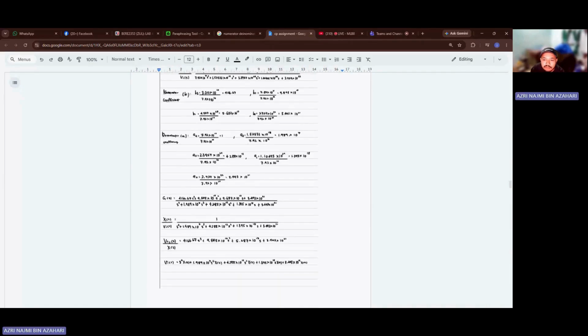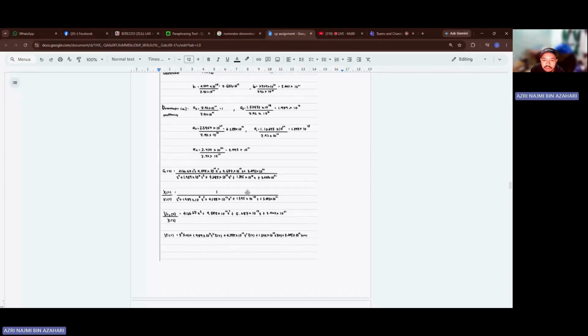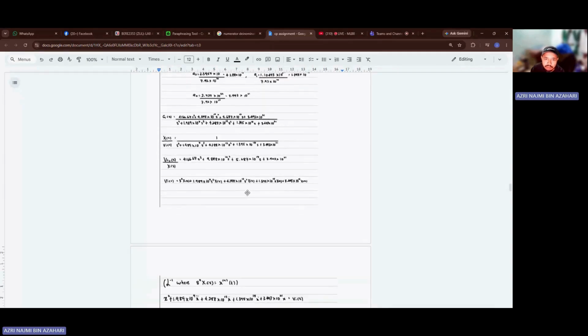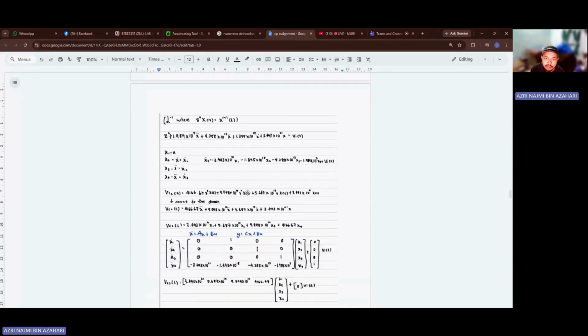By applying the inverse Laplace transform, the denominator polynomial is converted into a fourth-order differential equation. This allows us to define the state variables and prepare the system for state space representation. The resulting normalized transfer function and calculated coefficients form the foundation for deriving the state equation, output equation, and the state space matrices that will be presented on the next page. This is the next page.